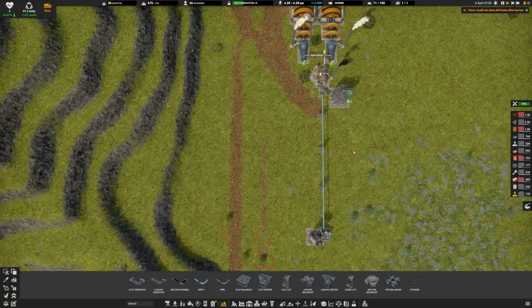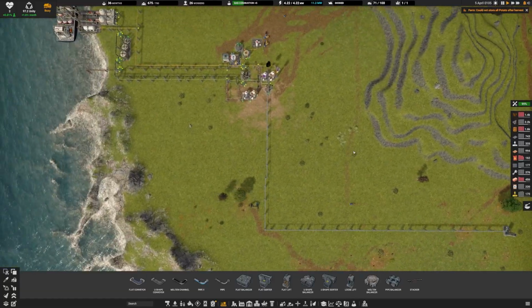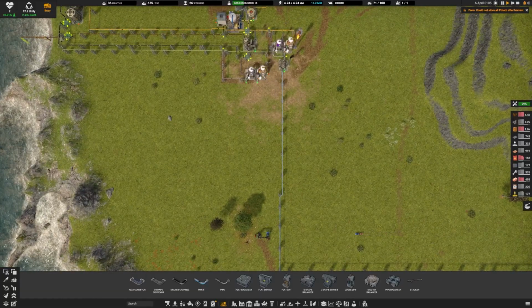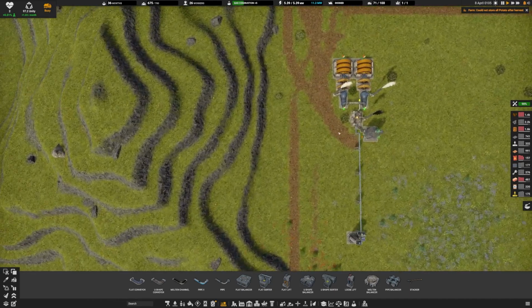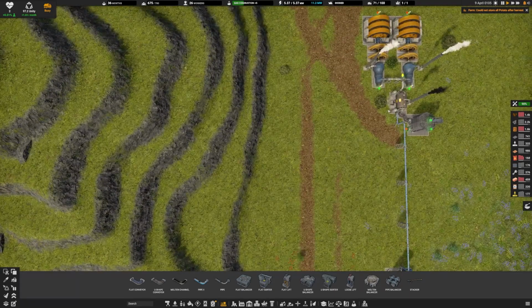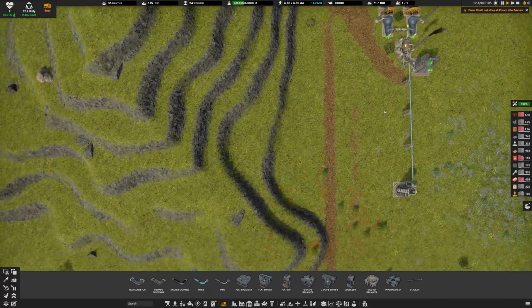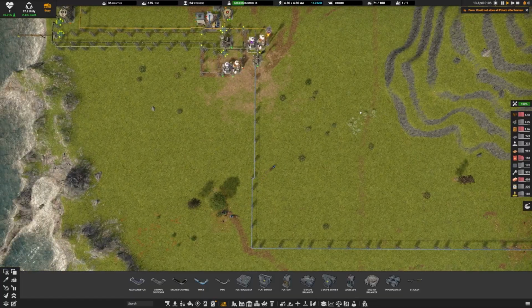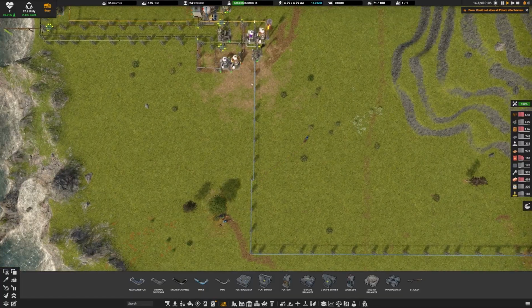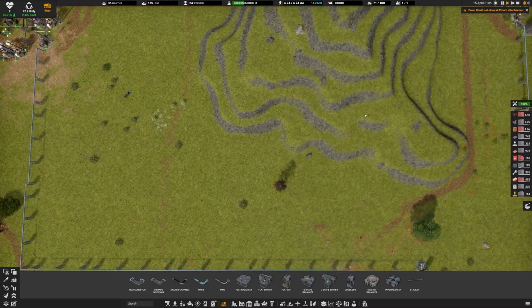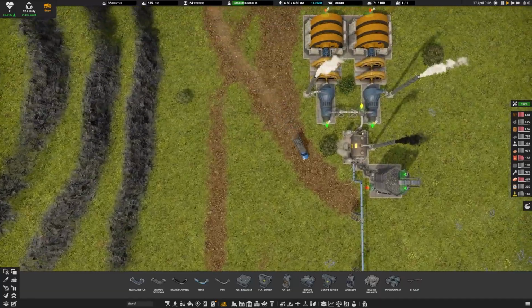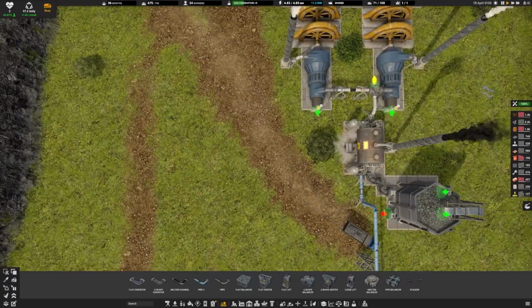The other thing we can potentially do is this outgassing. We can use it over here as well. We can do a supplemental steam over here to feed steam in. In fact, when we run the 2 boilers here, we can run a steam line over to here to supplement this steam.